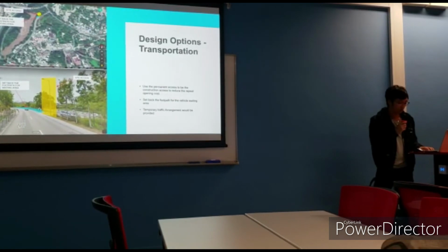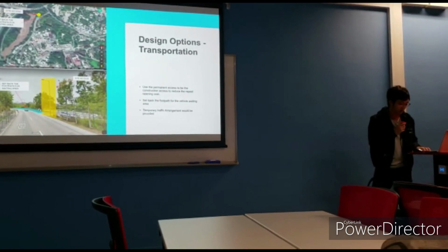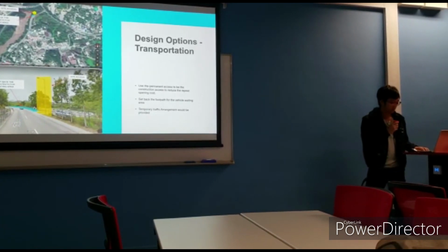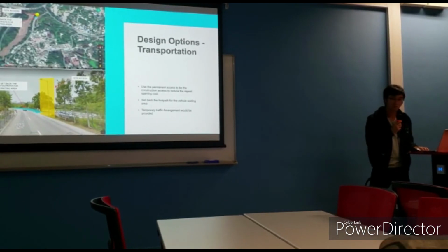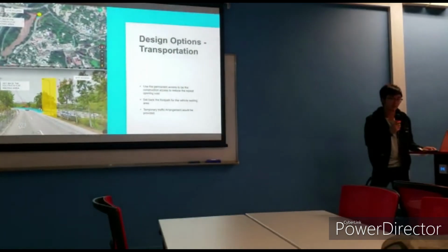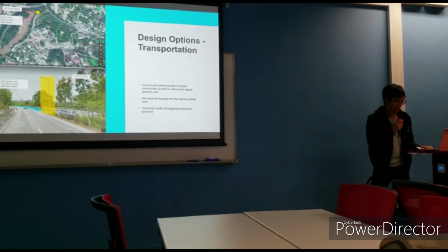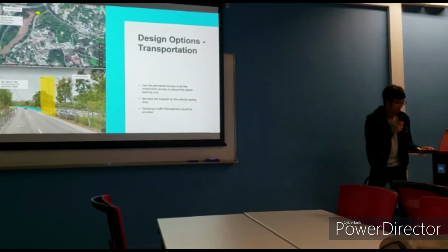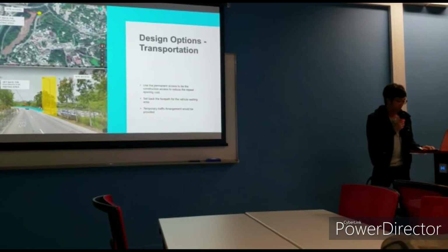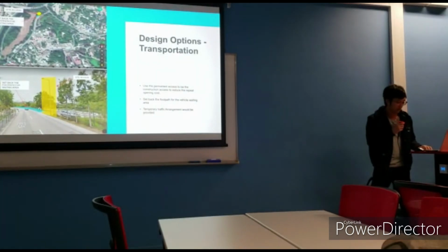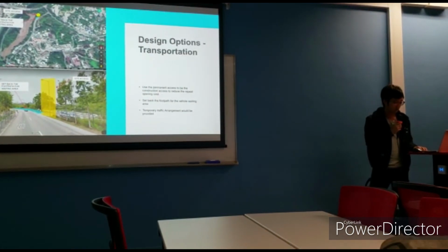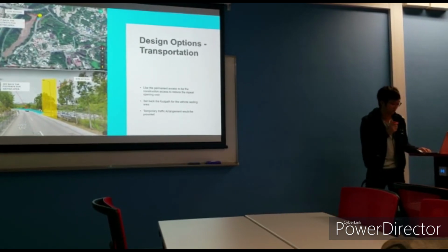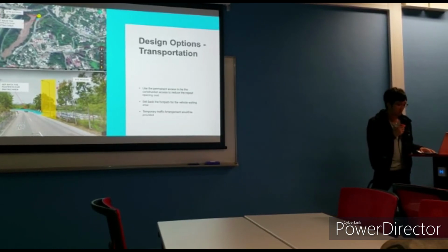The access is far away from the labor houses, but the home toll road is a one-lane, two-way road. Our access is close to the end of the turning. It will easily cause traffic accidents. So we would like to propose to set back the footpath to form a waiting area for the construction vehicle and temporarily divert the person to use the opposite footway. It can reduce the effect to the labor and be more safe, as there will be many heavy vehicles in the construction stage.